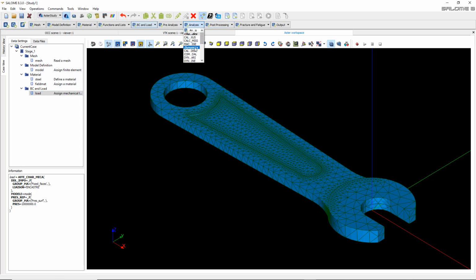Code Aster supports several types of study, and actually quite a lot. It has dynamic, it has static, it has modal and thermics. So this is static, so you have to go into the small static, and this should be this one, static mechanical analysis, Meca static.